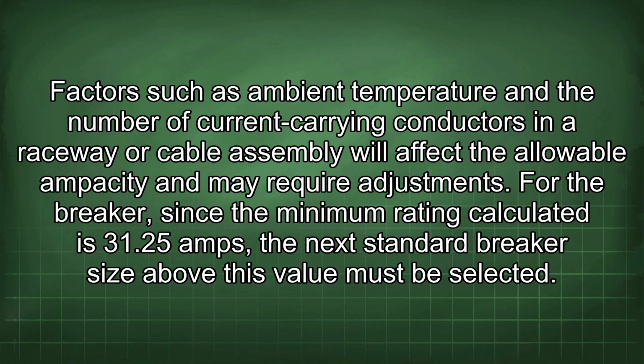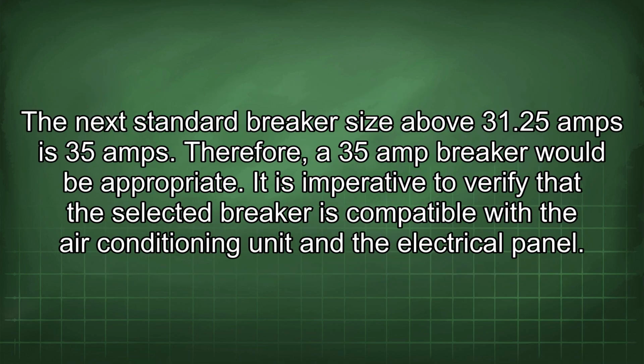For the breaker, since the minimum rating calculated is 31.25 amps, the next standard breaker size above this value must be selected. The next standard breaker size above 31.25 amps is 35 amps. Therefore, a 35 amp breaker would be appropriate.